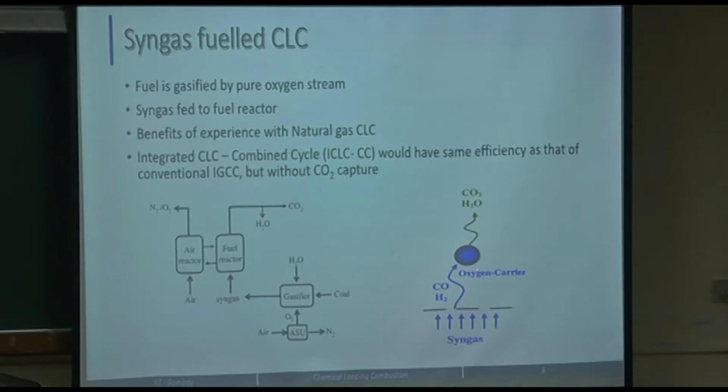So the oxygen carrier has a redox reaction with the volatiles and the H2 also. As per the studies done, if the similar concept of IGCC is applied with the integrated CLC combined cycle, ICLC-CC, it would have the same efficiency as that of the conventional IGCC, but without CO2 capture. So this is the advantage which CLC can give us.